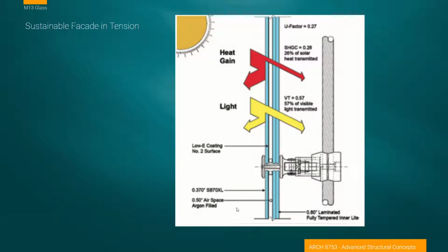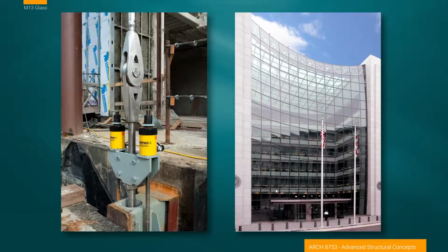And always when we talk about thermally high performing glass, we have to have a void space. We fill that with argon because it's inert, but we also have these issues of what happens when we make penetrations in the glass. How do we keep this seal solid, and what are the complications that come along with aligning glass that has holes in it? Enough on this one though, but one more thing is this idea of laminated glass. We have two pieces of glass laminated together to create extra amounts of structure in the glass.